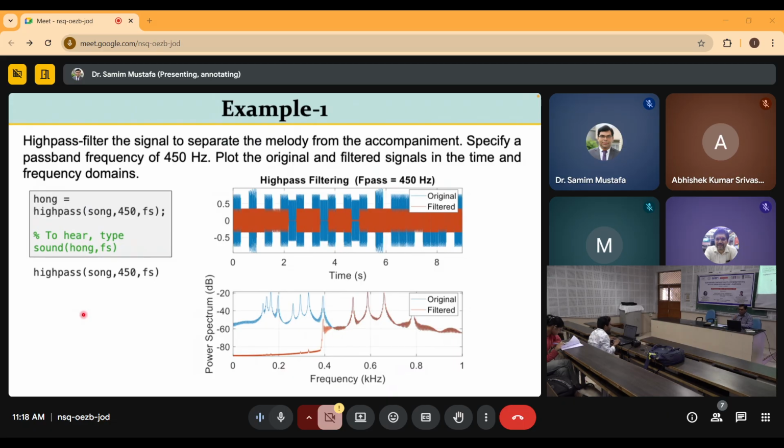So we want to eliminate the frequencies above that one from the response to preserve only the static part. Okay, so if you are using high pass filtering, then you apply the high pass and then deduct it from the total response. That will give you the low pass data, means frequency contained below the fundamental frequency of the bridge will be preserved and the rest will be eliminated. Okay, because it is produced by the dynamic component of the bridge.